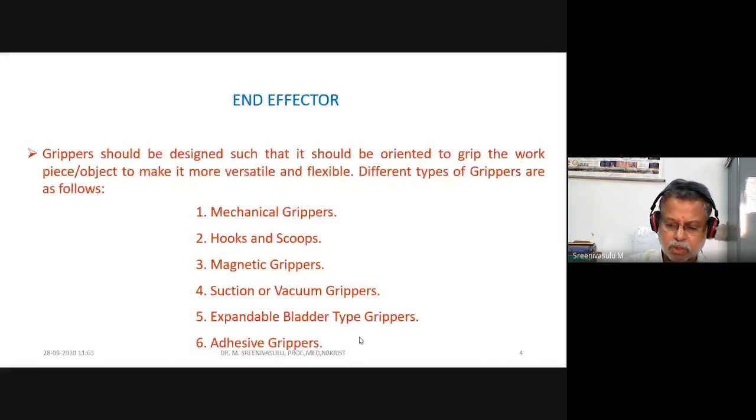it's not going to be. That too, you'll have to move your hand maintaining the same gap between the pieces you are trying to weld and the space you are trying to maintain over there. Simultaneously, that welding rod will be spending its flux. It's going to deplete. Slowly, its length is going to reduce while you are continuing your welding. While moving, your hand also should make horizontal movement and vertical movement simultaneously. I am trying to give you the complexity associated with welding.